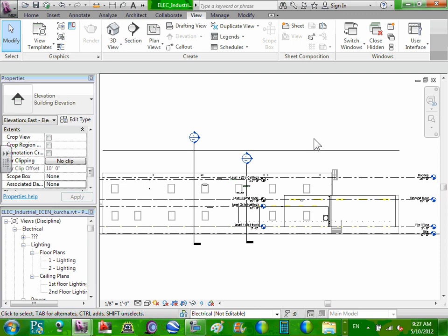Work planes are nice. You just won't have the option to build any floor on them. So if you were to put in another level that you called something like lighting height and associated all your light fixtures to that, somebody could make a floor plan out of a level, I guess.